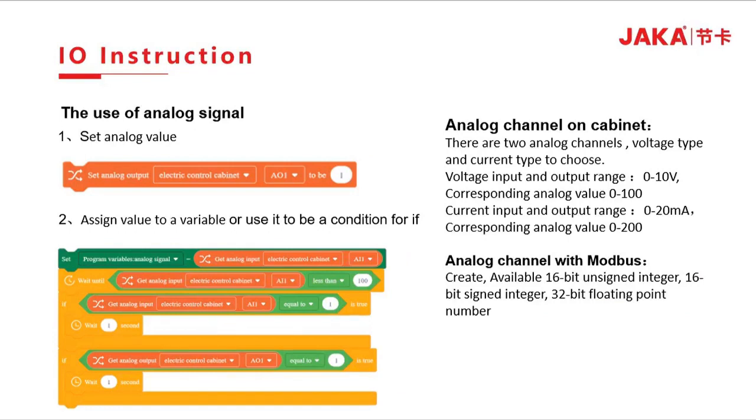The use of analog signal function is as previous. You can change on the drop-down list if we use a tool end or cabinet plug according to where our tool is set. Then you can choose which DO number you want to set, and finally you can set the value you want for the operation. On the lower section you can observe the main operations you can create with the judgment instructions.